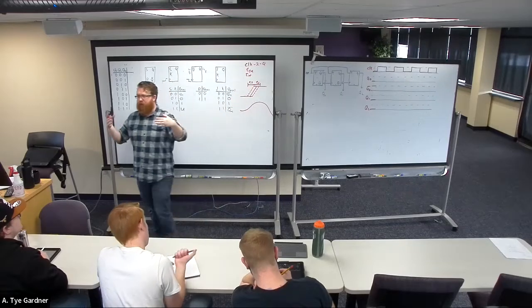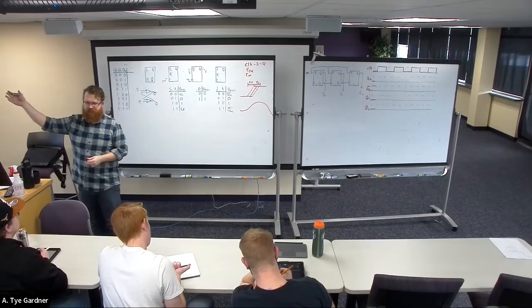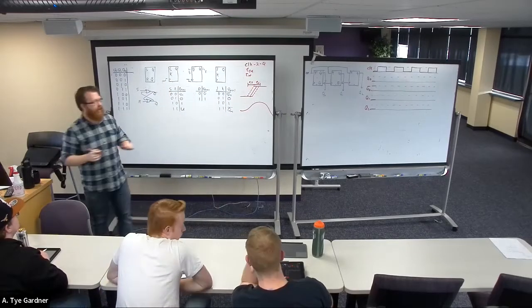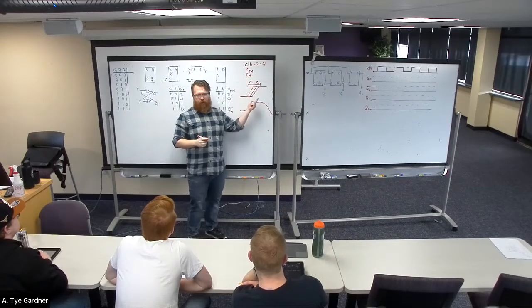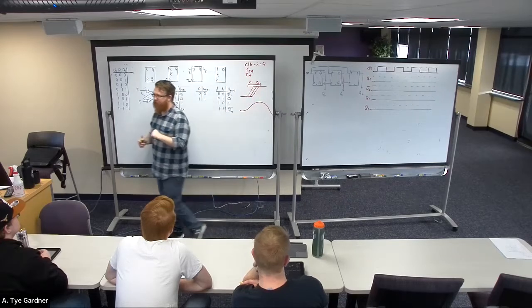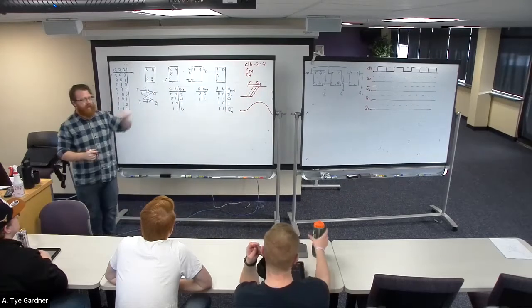So we have to rely on some device physicist who gave us the components to tell us what the setup time and hold time are, and then we just make sure we meet those. We don't have to understand yet why that's happening. We just have to trust that the other engineers know what they're doing, and as long as we meet those, it will behave correctly.